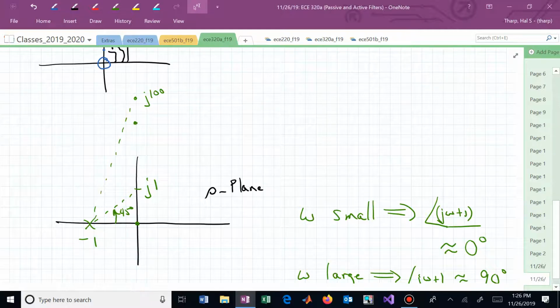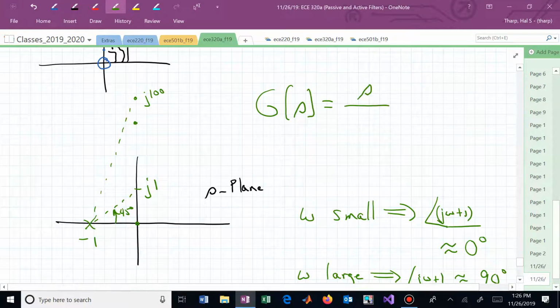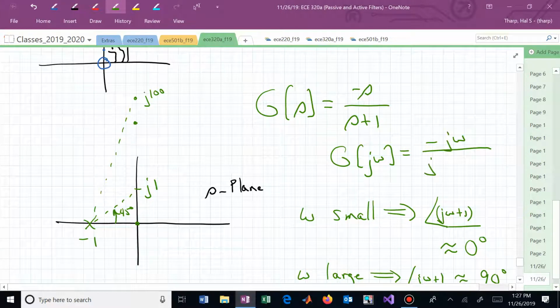And in the frequency domain, when we're thinking frequency response, so if we had some G of s, in this case we are replacing s with j omega, and now we just worry about what that complex number equals at various frequencies omega, where those frequencies are going from DC 0 up to infinity, omega getting large. Not sure, did that answer your question?